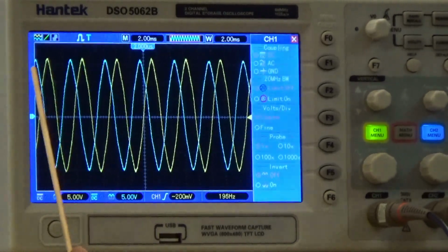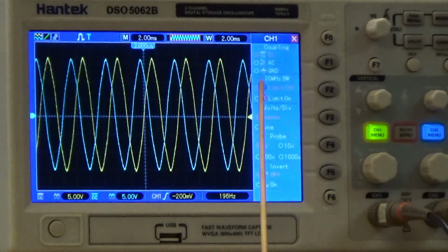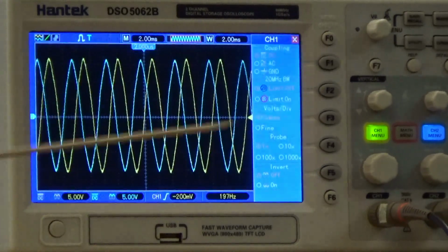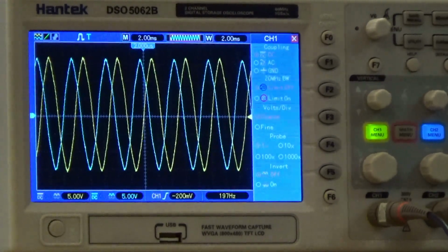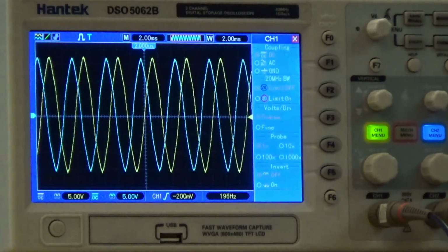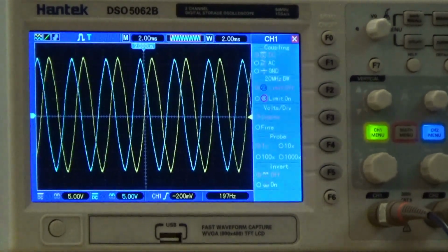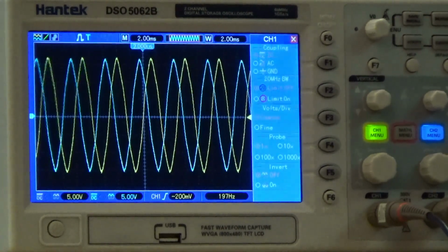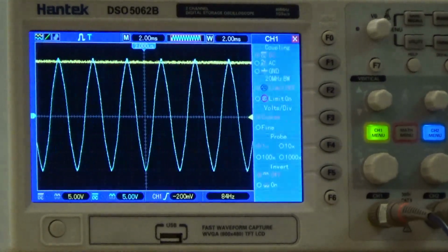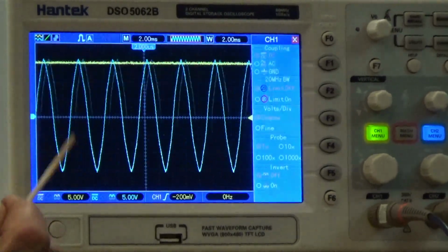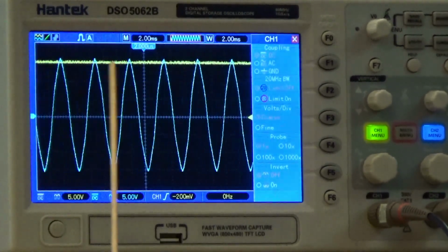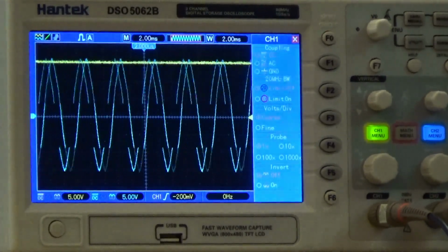And so you'd have 3 very evenly spaced alternating current sine waves. Now those are fed through diodes, which convert alternating current into direct current. And I'm going to flip the switch here, and we will compare a single phase with the direct current. So here's our single alternating current sine wave, and there's the direct current voltage that's being provided.